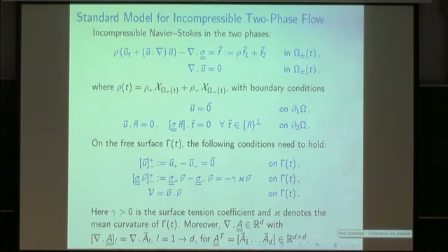Can I ask a question? Yeah. If you have a lateral gradient of surface tension along the boundary, you will probably have tangential flow. Yeah. So then we get Marangoni forces in here. No, so this is normal. This is in the normal direction, right? And the force balance, yeah, force balance in the tangential direction on the interface. So if you have a gradient of tension, usually no compensation by any curvature term, you're supposed to have something like Marangoni flow. Is it somehow taken into account?